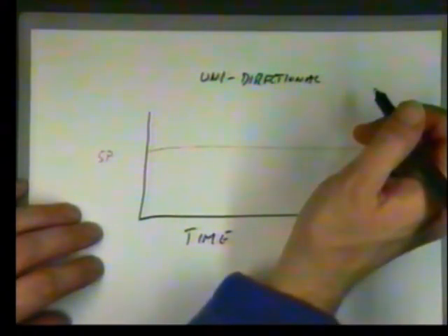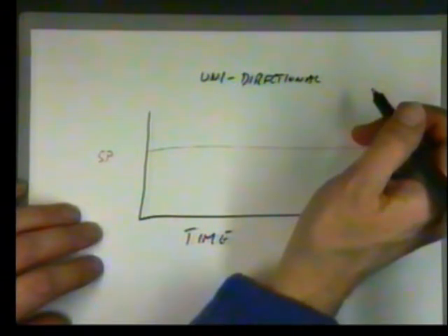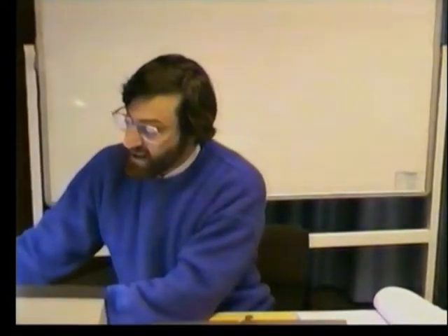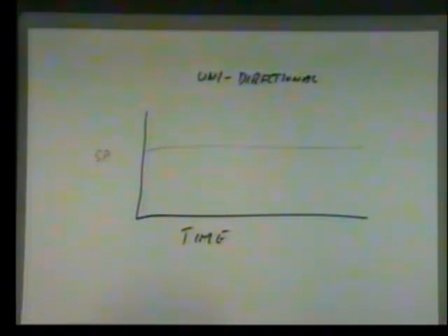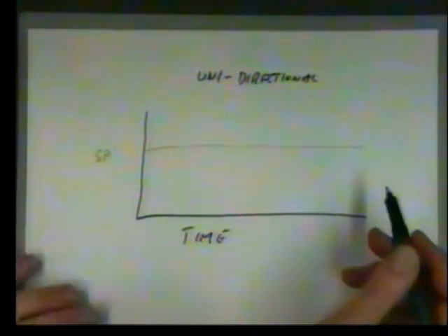So it's a single heater, or it's the air conditioning, or it's a motor that only moves one way. So you can only drive things in one direction. You have to rely on natural cooling or heating, slow processes to drive things back to rest. Now, if we were to try and control to this as it stands, we could end up hunting.